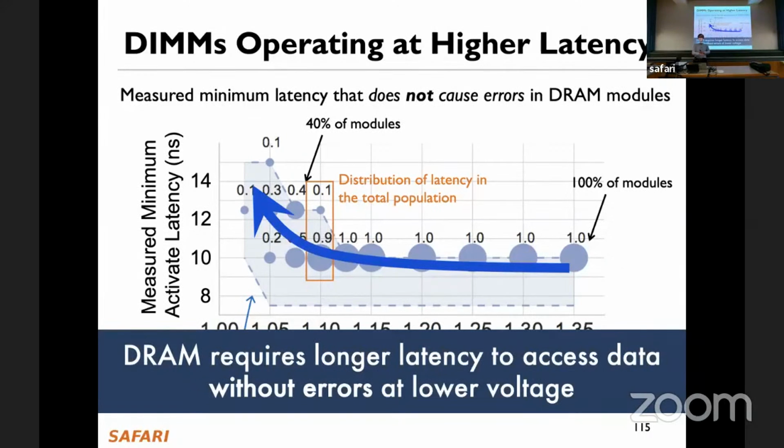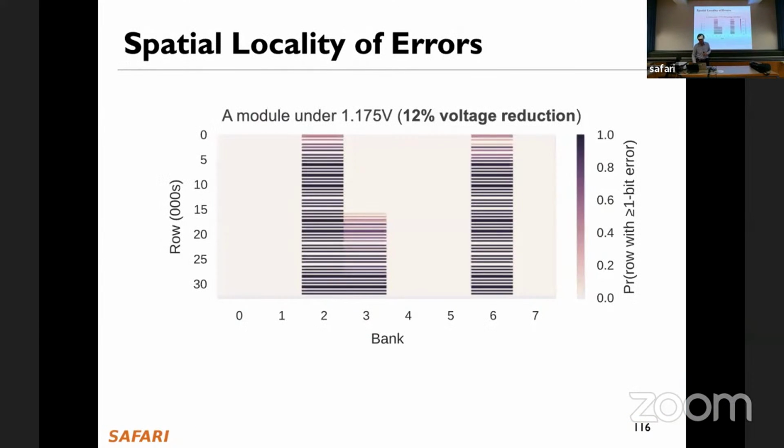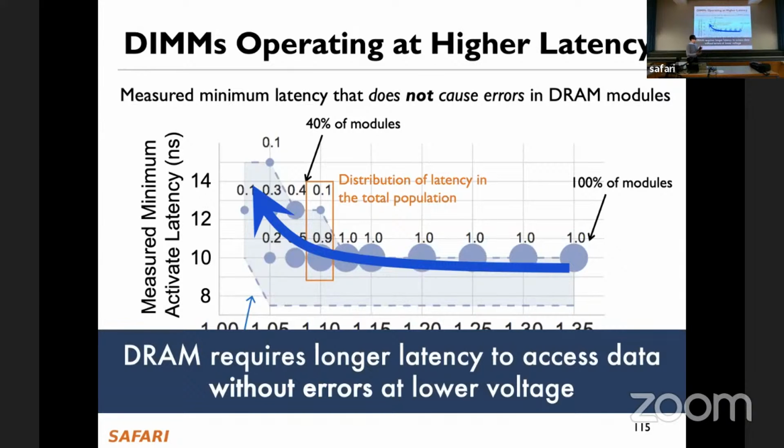And you can actually calibrate. If you have an infrastructure like this, you can calibrate your circuit level simulations using the data that you get from the infrastructure. That's actually very, very valuable, because otherwise you just do simulation and you don't close the loop, right? Here we can close the loop, meaning we can keep calibrating our circuit level simulations. So that's one observation.